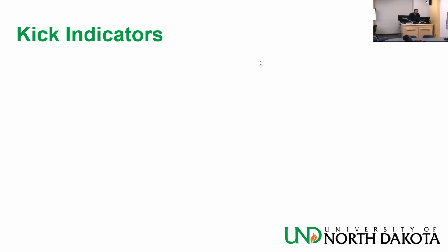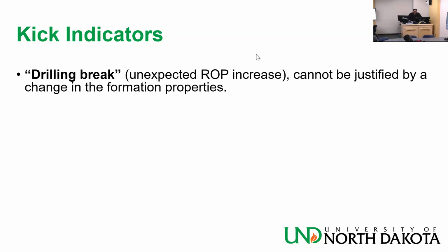And when drilling, you look at the ROP. If you suddenly get an ROP increase, it could be because you switched from a hard formation to a soft formation, and that's okay. But it could be because you are taking a kick. The kick helps remove rock, so it looks like it helps you drill, but it's not really, you are taking a kick.